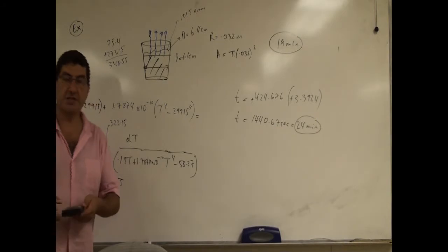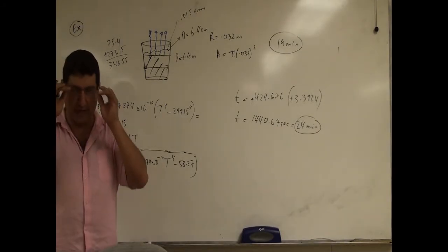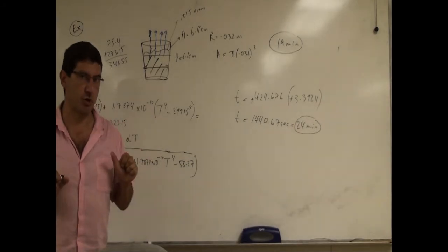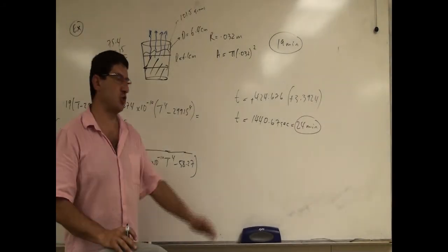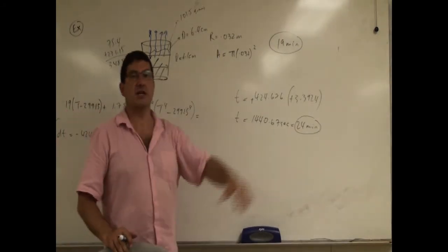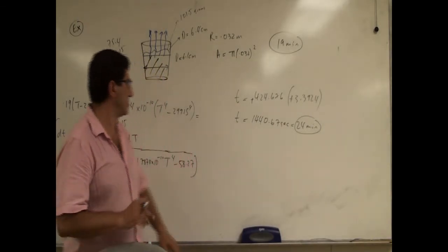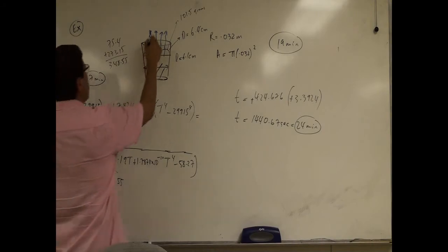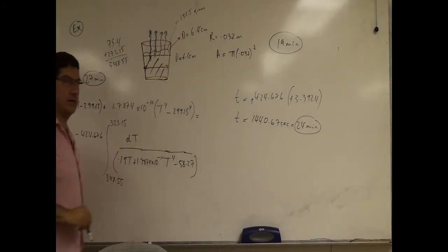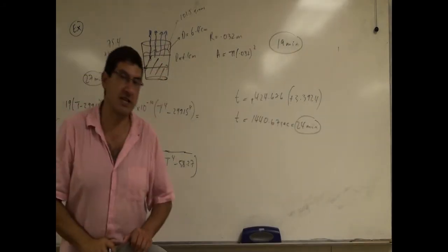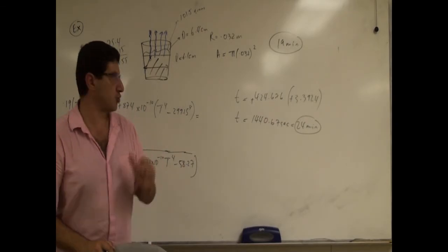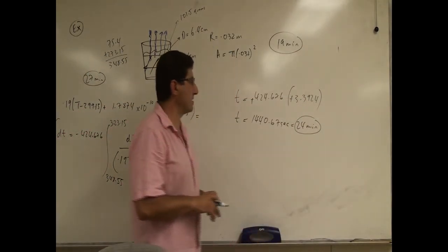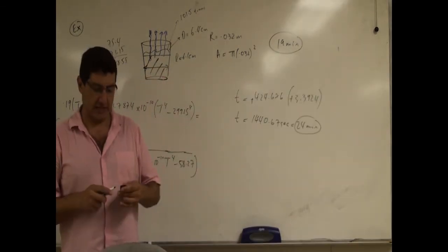Okay? So it does reduce the time quite a bit, right? So with just conduction alone, it predicted that it should reach 50 Celsius in 27 minutes, right? 27 minutes. Now, if I include the radiation through the top of the cup, it's predicting 3 minutes faster. So 24 minutes. Now, of course, when we ran the experiment, it took 19 minutes, okay?